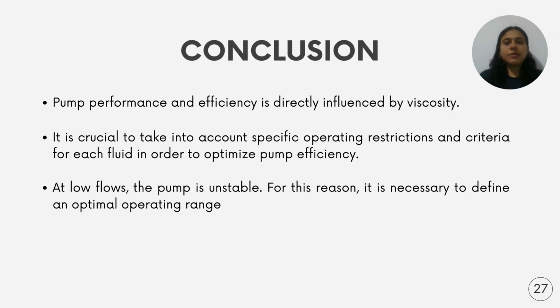It is evident that pump performance and efficiency is directly influenced by viscosity. At higher viscosity, the pump efficiency decreases. It is important to mention that pumps must be specifically designed for the fluid to be pumped. For this, it is crucial to take into account specific operating restrictions and criteria for each fluid in order to optimize pump efficiency. Likewise, it is important to mention that at low flows, the pump is unstable. For this reason, it is necessary to define an optimal operating range.